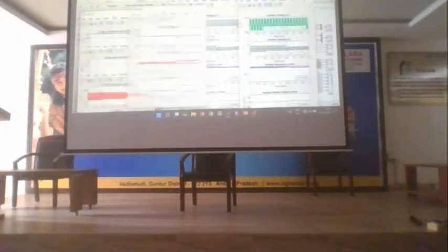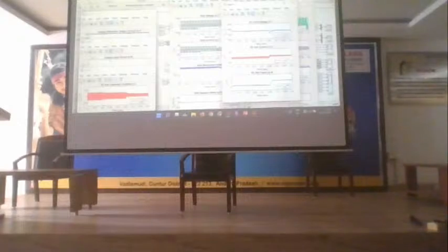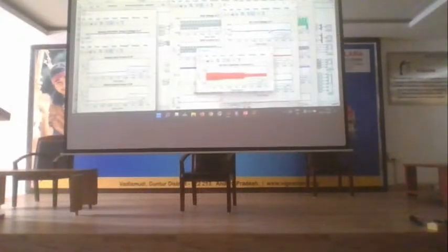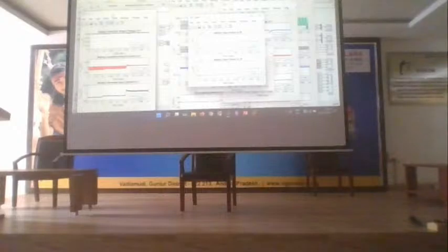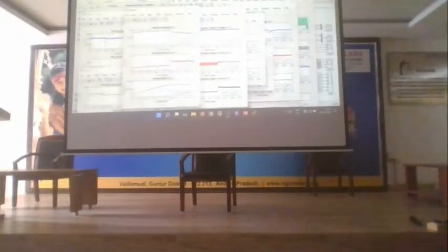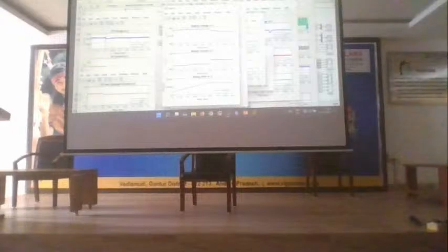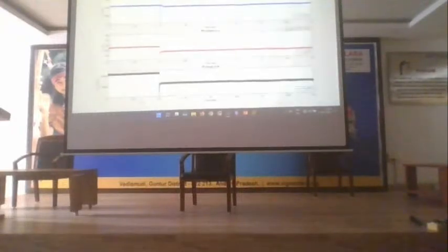I'm going to plot the graphs. You can see that. Alright, first let me show my PV results. You see that initially it is the extracted power of 10.5 kilowatt. And at 0.2 I decreased my irradiation, that's why my PV power decreased. It is now about 5800. Since I have decreased my irradiation, accordingly my current goes down.